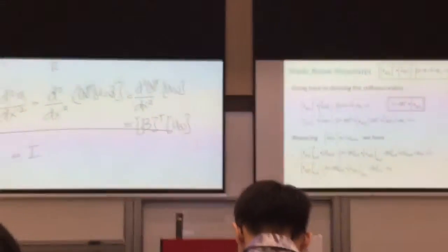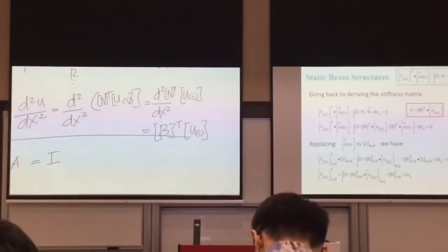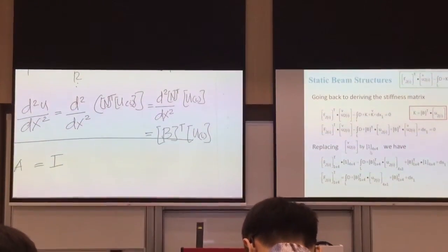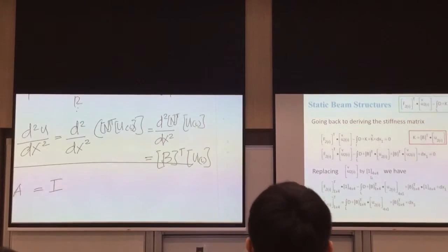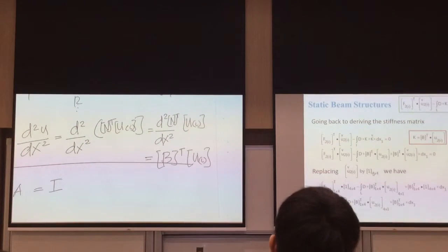Since our total degree of freedom per element is 4, one displacement, one slope per node, so that's 2 multiplied by 2. So we have now this one to be an identity matrix of 4 by 4. So you multiply 1 with this guy, multiply 1 with this guy, then it's the same value. There. And this one again is a scalar value.